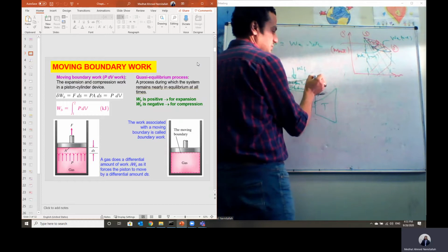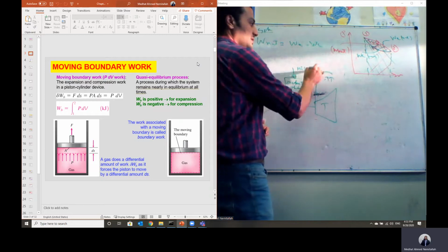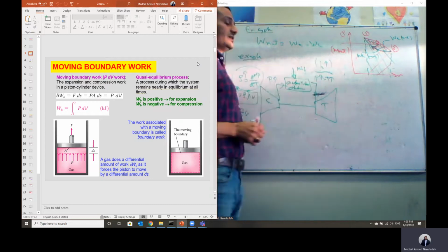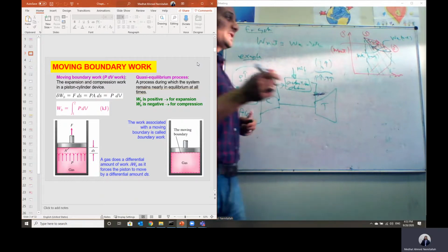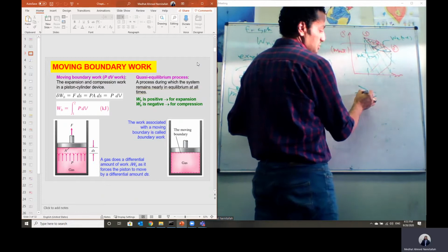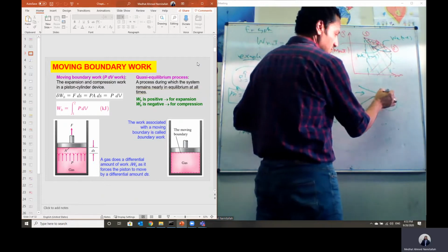At the exit of this combustion chamber, we will have exhaust gases at high pressure and high temperature, or high enthalpy. High pressure, high temperature, so we have gases under high enthalpy in this case. Then we can pass them through the turbine. The turbine has a fixed blade and a moving blade. The fixed blade is the nozzle, and we have moving blades having buckets. Then this